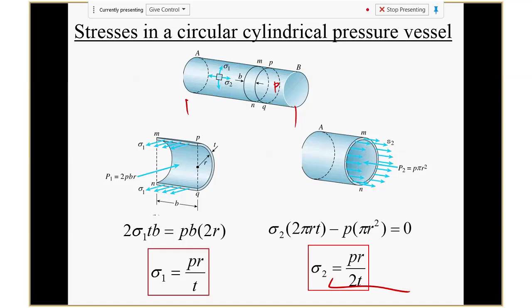Does the shape of the Coke can matter? Like, the Coke can has a dome bottom, so it's not the same. Well, that's slightly different because it's a detail of the shape, which causes some stress difference. So we talk about the perfect ideal situation: a nice cylinder with perfectly flat ends. Also, remember, we talk about small deformation. We ignore the edge effect and the stress concentration.